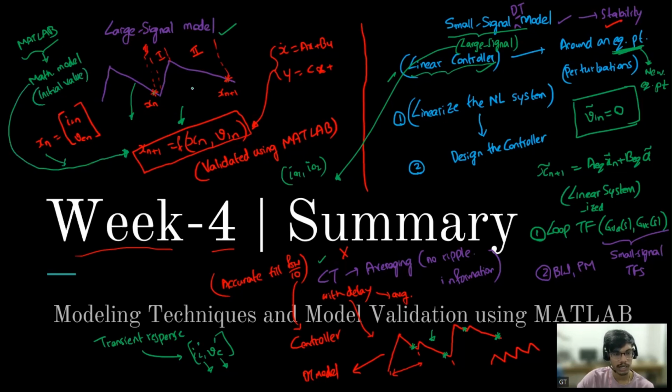I know that it will be a triangular waveform and it has 3 different regions: mode 2, mode 1, mode 2. So I am using the actual state space equations, and I get an expression for xn plus 1. If I give this initial condition to my buck converter for these operating conditions, I know that at xn plus 1 this will be my inductor current, because the equations say so. MATLAB in the Simulink model is also using some mathematical models. You understood, right, Rajshekhar?